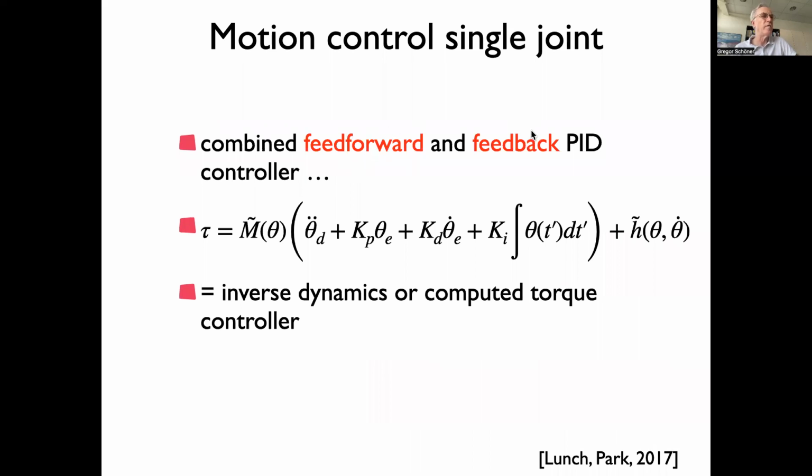You have a feed-forward and a feedback term. So what you will do is you say the torque I'm using is a torque that takes into account the prediction. So the desired torque times your model of the inertial term is a contribution, and you're also predicting the interaction torques. But then you're also inserting here a desired acceleration. This is a contribution to the acceleration that is feedback. That is, here you're putting the error in, the rate of change, and the integral of the error.